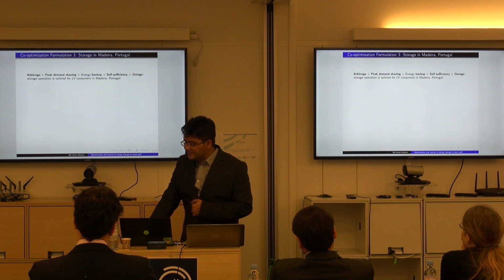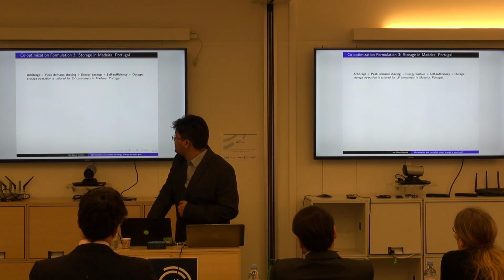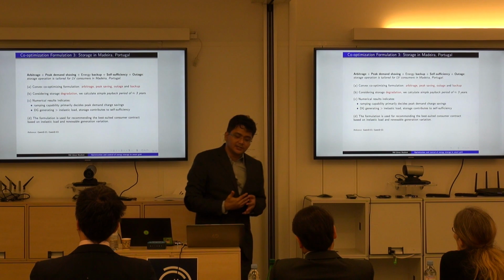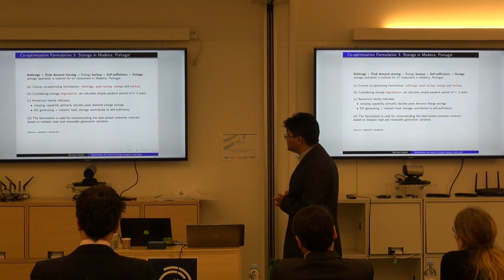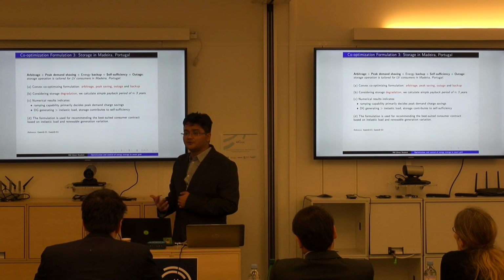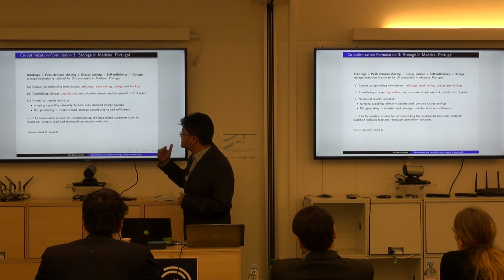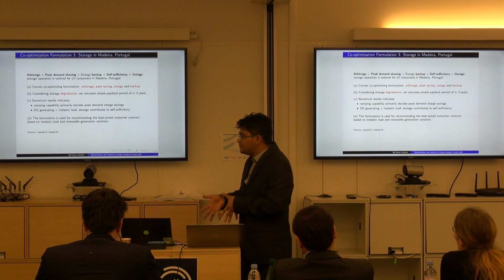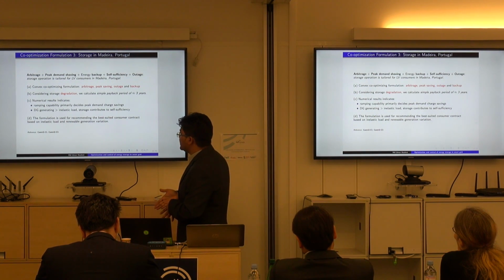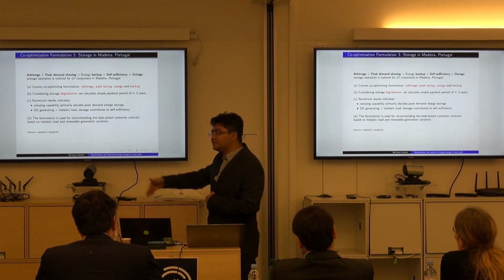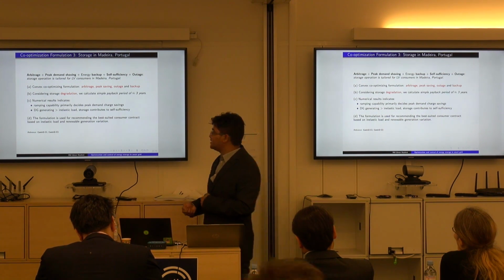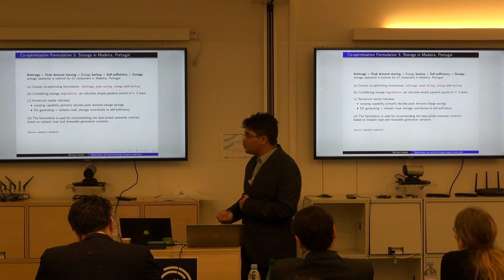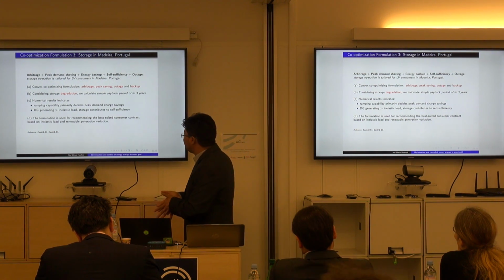So these are the goals for this setting, and using real data, we observe that this formulation can be done in a convex setting. And using numerical results, if we consider the degradation of the battery, we can calculate that the simple payback period for batteries is less than 3 years, which is amazing in this case. Some key numerical observations are that battery peak demand saving is directly governed by the ramping capability. It is less a factor of how big the battery is than of how much power it can ramp at a certain time. Now, whenever the DG at the home end is more than the inelastic load, then storage can be used for increasing self-sufficiency.